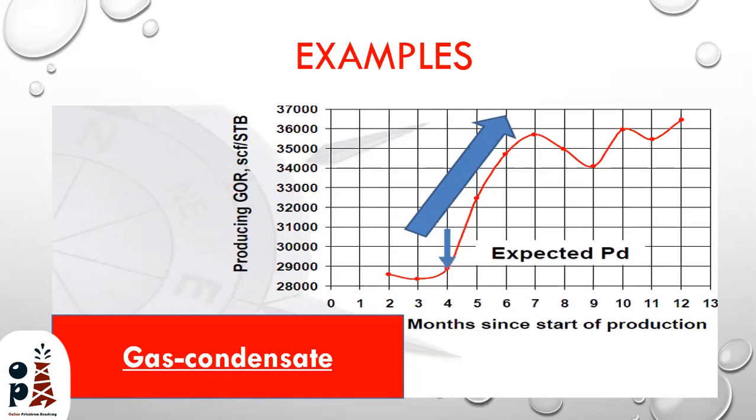Also, we can note that the GOR increased after some point, so we can expect that at this point the pressure declined below the dew point for this reservoir.